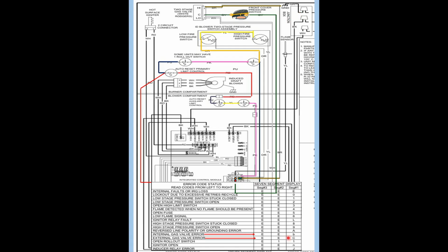And we see that we would get these internal gas valve error or external gas valve error, one of those. If it was actually reporting that the gas valve was closed, then it's going to give you those error codes because it shouldn't have that.